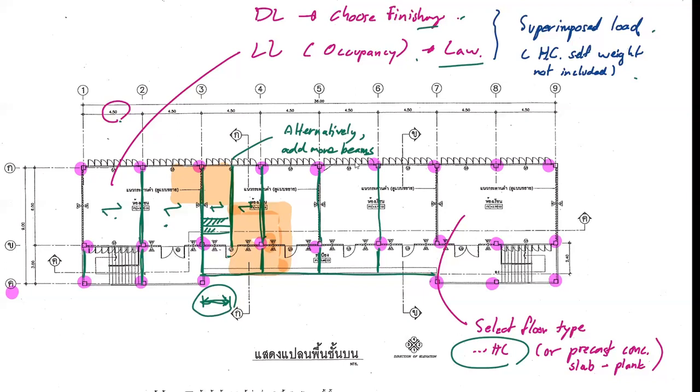Okay, it doesn't affect what we are doing at this stage yet, because you can just select the floor, you can select the load, and this one will remain the same. But let's say in the future, if you are equipped with the proper ability to handle the composite, you may say, I want the composite action, and therefore you can save the expense on the structure even further. But yeah, there's a pros and cons, because you have to pay for the shear connector as well, right?